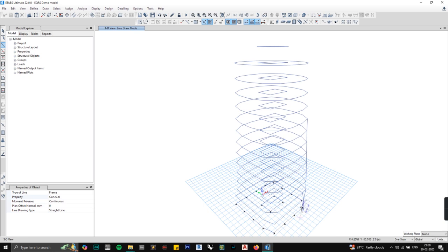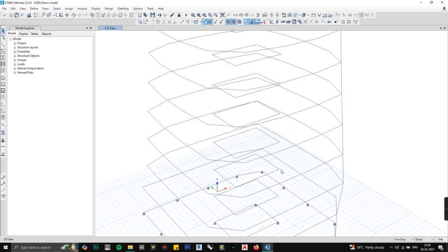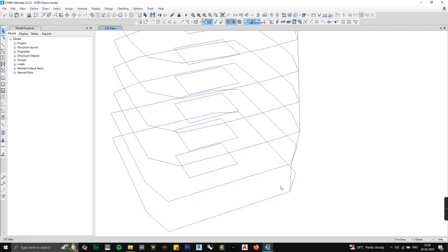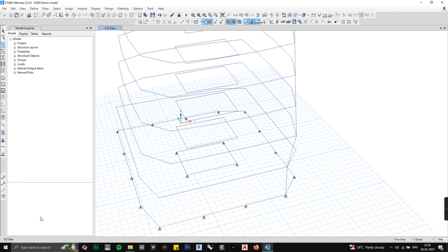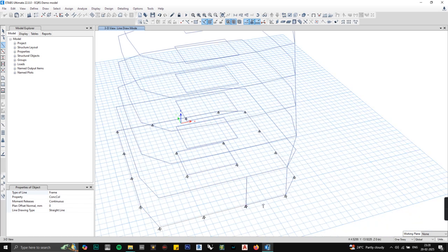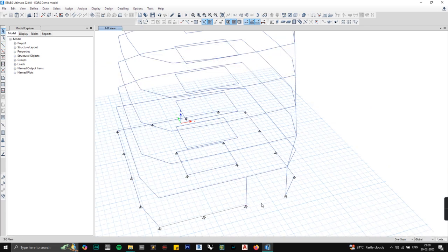Now what we're trying at the basement, or sorry, at the footing substructure level is I'm going to be deleting. So if I have drawn this in conc col, if I do something like this, I don't need this line, nothing needs to be connecting the footing. So we have only beam here, and this straight away is column goes to the footing. That's how you make columns.